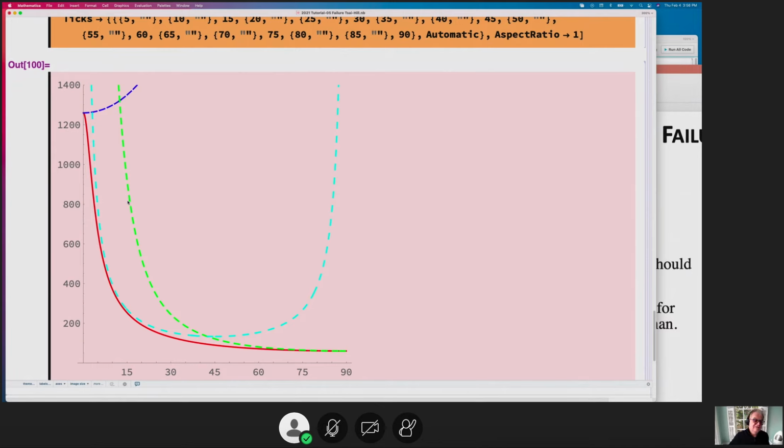At 15 degrees, this is where you're going to fail the matrix. But my Tsai-Hill, the red one, is the envelope. So you see actually Tsai-Hill takes into account this interaction between the stress along the fiber direction and stress in shear.